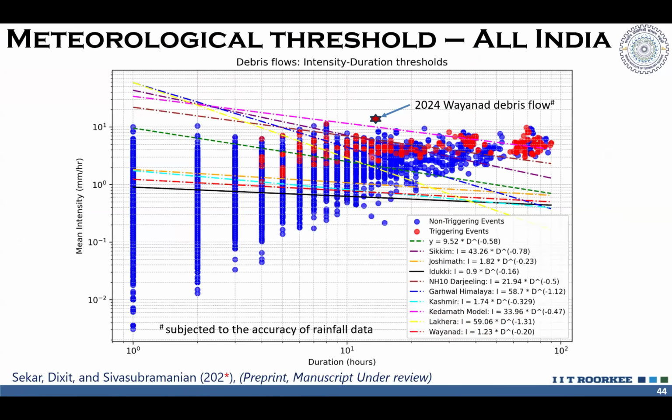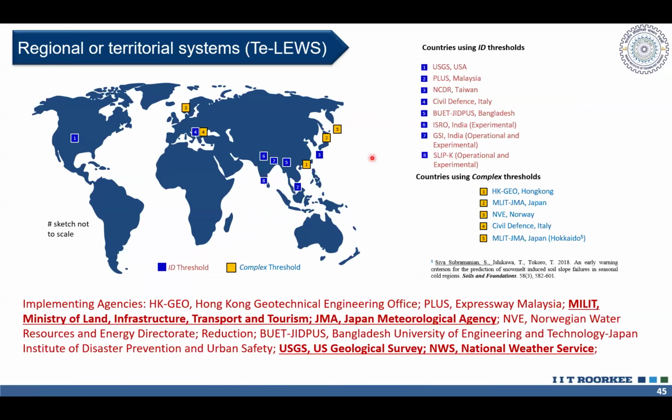Now we are moving from, let's say, fundamental geotechniques to early warning systems, where we move into meteorological and hydrometeorological thresholds for early warning of rainfall-induced landslides and debris flows across the Himalayas as well as in the Western Ghats. So this is a sketch of available information. The list is not exhaustive. There are different nations which inform people in an early warning system using a meteorological threshold, that is mainly based on the characteristics of the rainfall that is going to create a landslide.